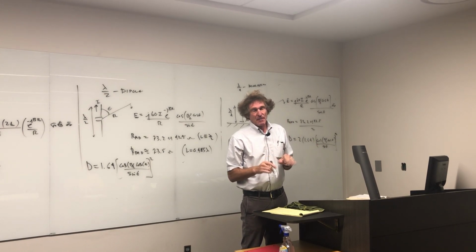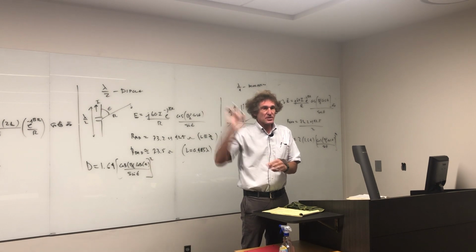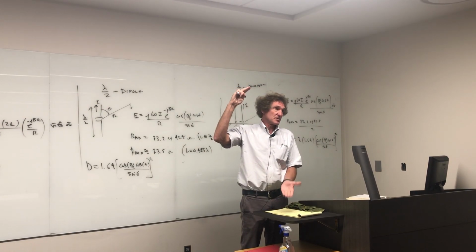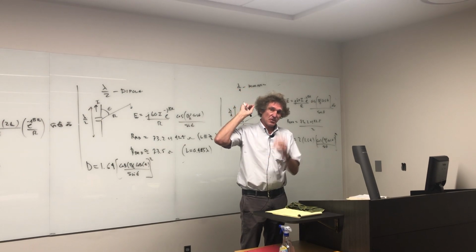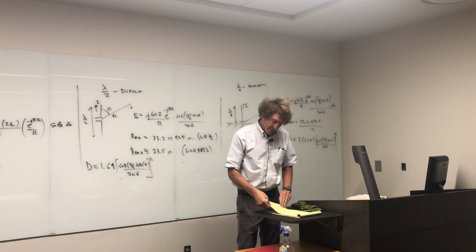I put it to you this way: electrolytics, I'll work around in TVs and stuff, and I have no problem, I'm not worried about them. Large electrolytic energy capacitors, I will not mess with those unless I know for sure that they're not charged, and if I have to discharge them, I'm going to do it safely. So that's my take on that.